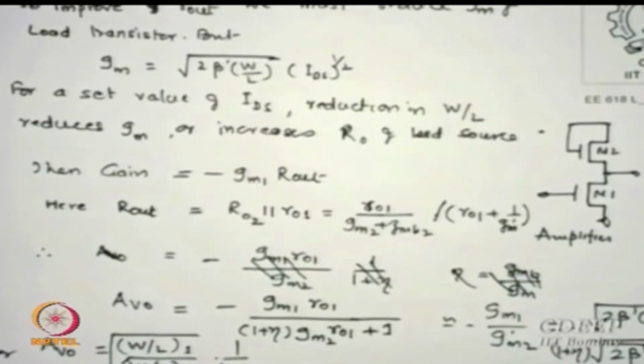That is the strength of diode connected loads for an amplifier. So the choice is not whether you should use or not, the choice is when to use; you should be aware of it. Is that point clear, why I showed you diode connected loads? Because one wants to know that just by adjusting the ratio I have control on the gain itself. Am I clear of what I am saying?